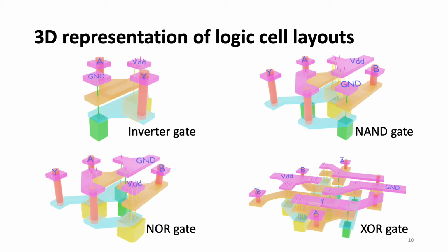In these structures, we applied equivalent scaling to balance pull-up and pull-down branches through the number of vertical nanowire channels per transistor, typically 1 versus 3 for N versus P. We also made some assumptions about the physical design which can be seen in the structure. In particular, we use 40-degree routing which enables compact circuits. We also set power and data input-output contacts at the same top level.